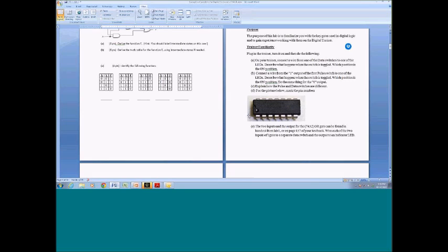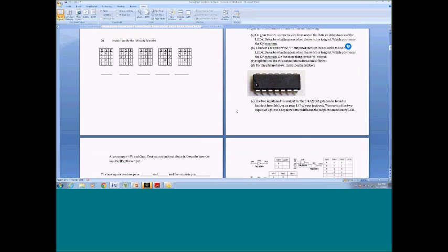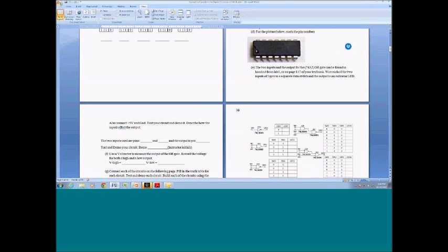But we do talk about the pin packages and the numbering, and where VCC and ground are. Many of them learn quickly that if you flip this thing over, you short the thing out, that you've hooked VCC to ground and vice versa. Many students, and this happens a lot on their trainers, will at one point or another hook power to ground and blow their power regulator. That happens so often I lost count.